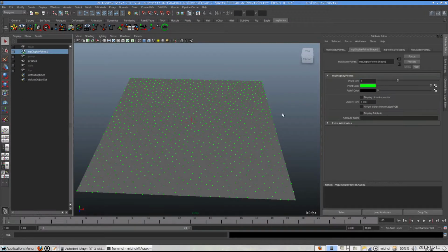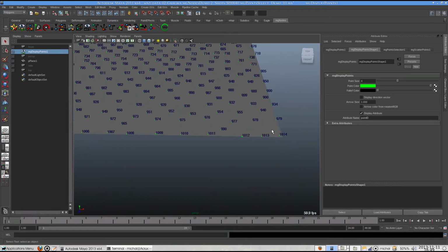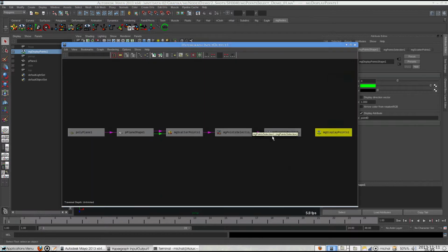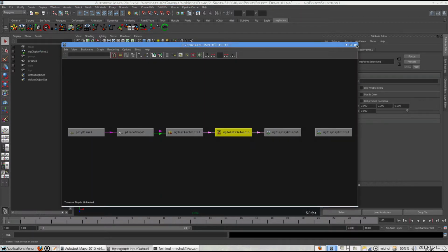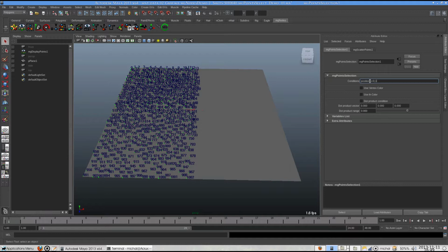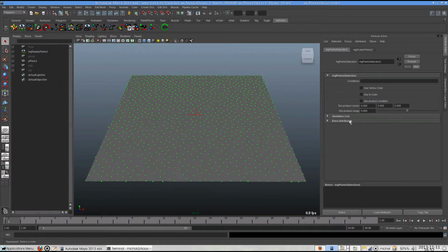We can select points based on their attributes. To select points, specify condition in mgPointSelection node. If you want to add some specific points, you can add ID in condition string, separated by comma. Color-based selection is possible. Method is the same as presented in previous chapters.